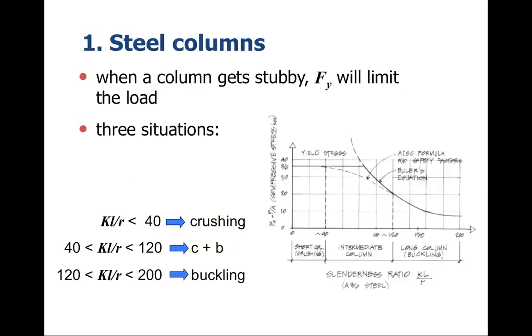All right, some other things related to steel columns. When the column gets short and stubby, F sub y will limit the load. F sub y being the allowable stress in crushing. All right, so we have three situations. One where K times L divided by R is less than 40. Here we have the crushing response. This would be in this particular zone right here.